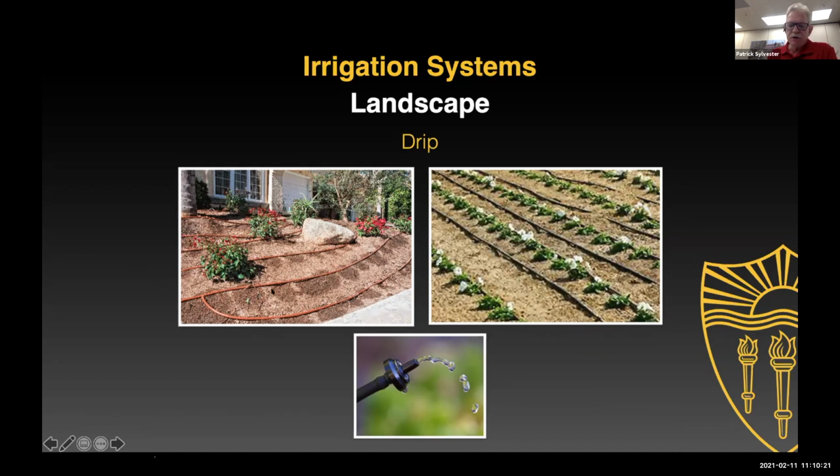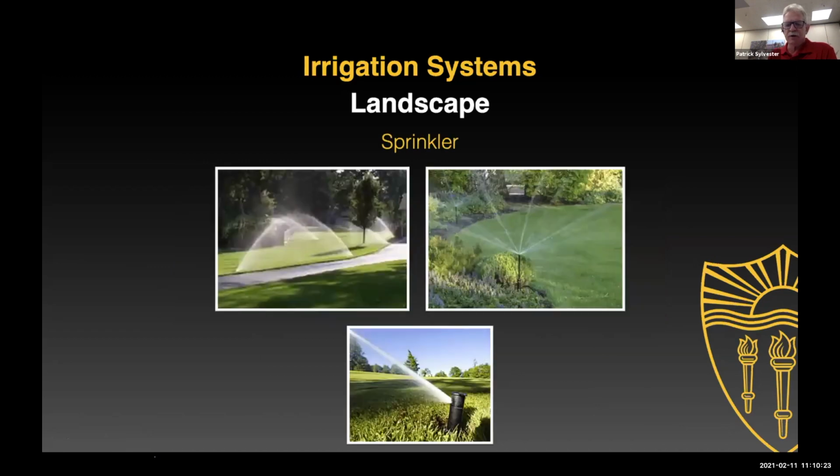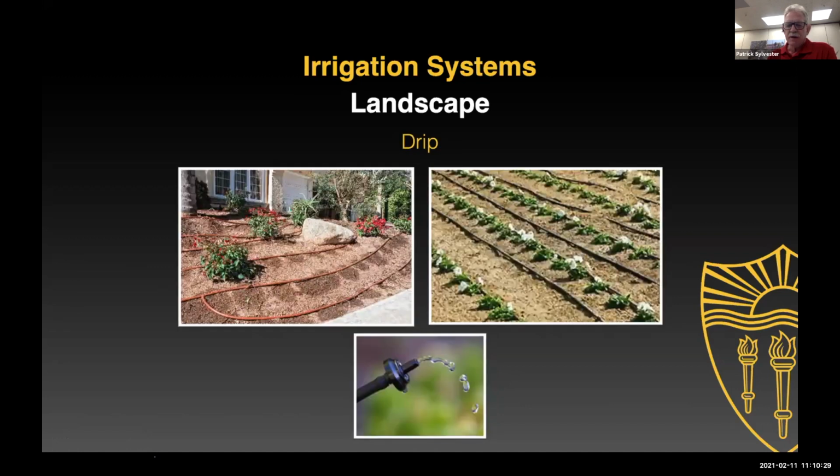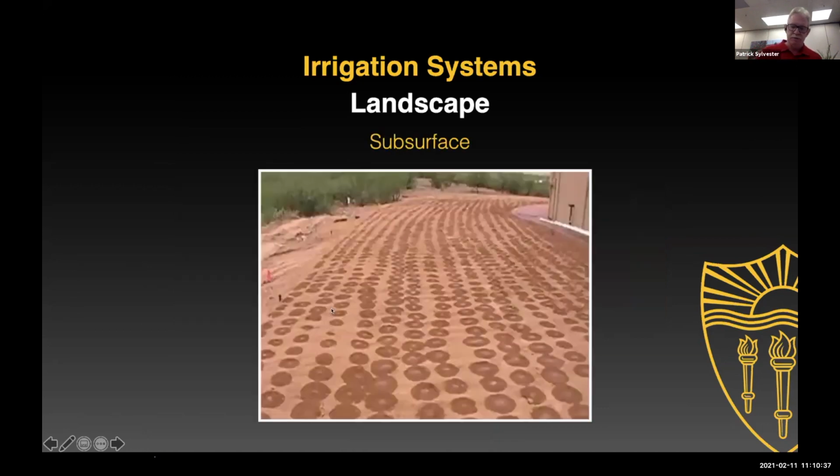So again, in these situations, we want to look at is there a hazard here if we're not using chemicals or fertilizer? Now, I think we see a problem here because, of course, if your water line is underground and it's got an opening to the surrounding ground area, any contaminants on the ground could soak down in and get into that water system. So that is certainly a concern.